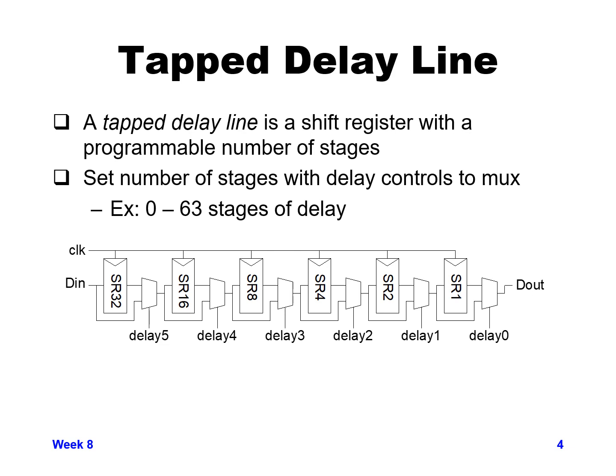And of course, depending on how we program the 6 different muxes, we can get anywhere from 0 cycles of delay to 63 cycles worth of delay. So make sure you understand that. Should be a relatively simple concept, but if you want to go through it, pause here and you can go through it in more detail.